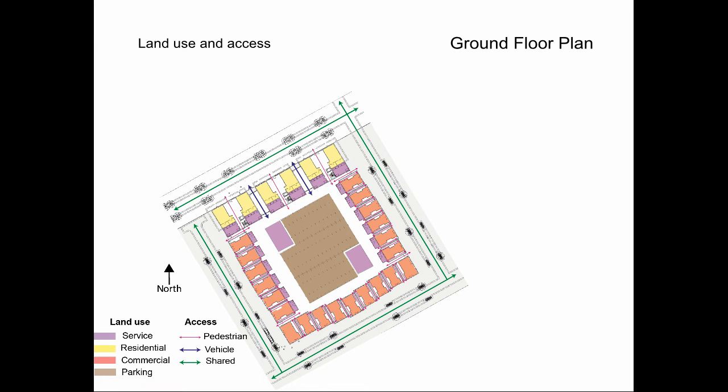The commercial units provide active frontage and overlooking in the eastern, western, and southern side. The easy access and the servicing area towards the back means that human activity is expected to occur at the rear, which should provide periodical overlooking and surveillance. Similarly, the single-aspect residential units should provide active frontage and surveillance in the northern side.